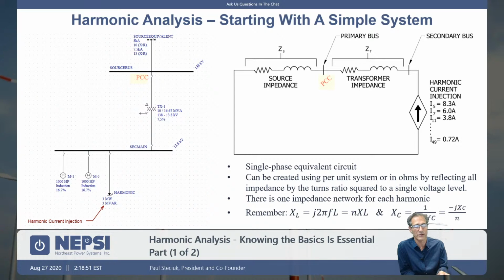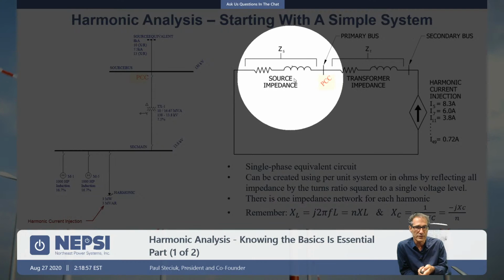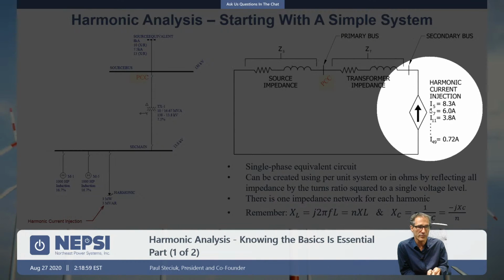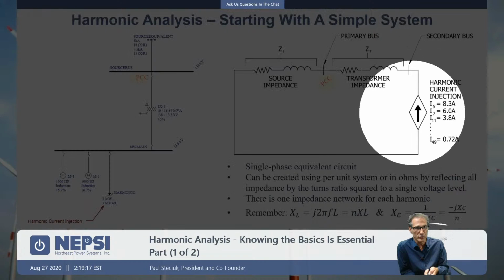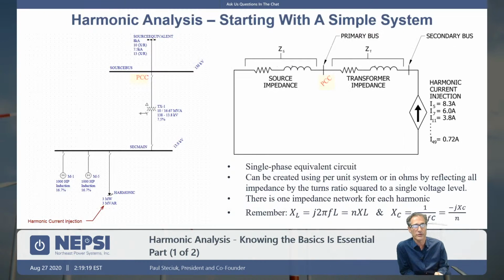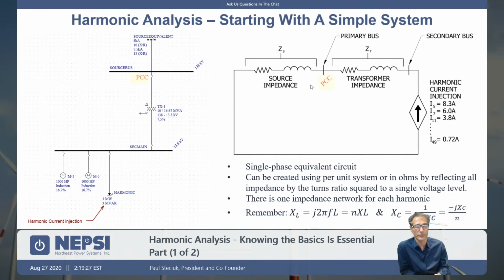They're ideal current values, which means that no matter what these impedance values are here, that amount of harmonic current flows, much like a CT secondary if you think about a current transformer. No matter what the primary current is through the window of the CT, the secondary current is a ratio of that, and it's being injected into the metering devices. In this case, the fifth harmonic would represent 5 times 60, 300 hertz. It'd be 8.3 amps. And no matter what this impedance is, to repeat it again, we would have 8.3 amps.